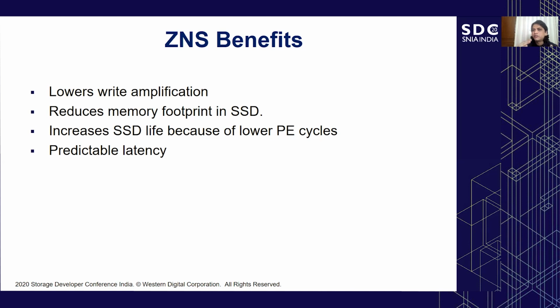Typically the erase latency and the write latency is huge compared to a read latency on an SSD, and these GC activities increase the tail latency of the read requests, and that shows a very bad performance at the host level.